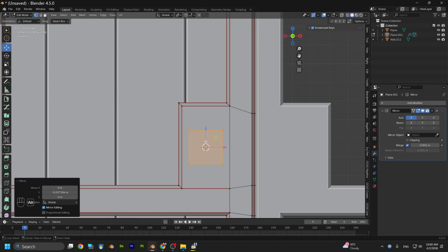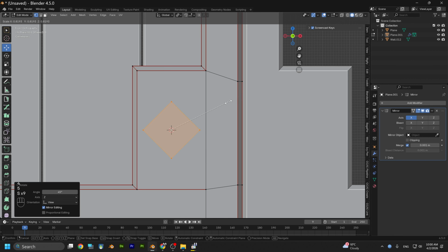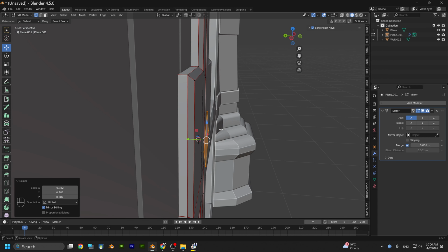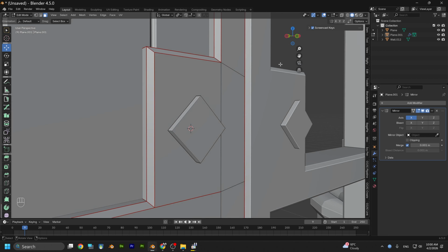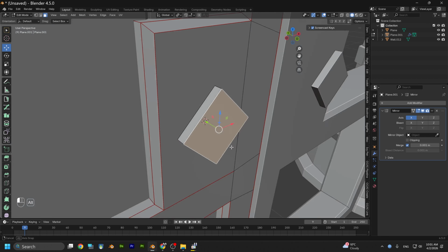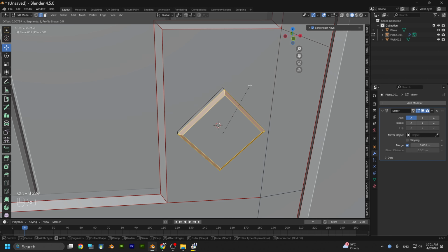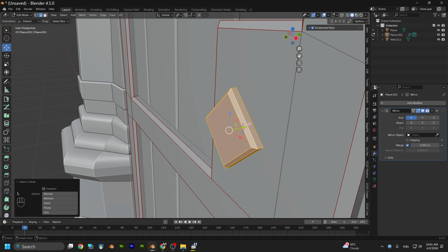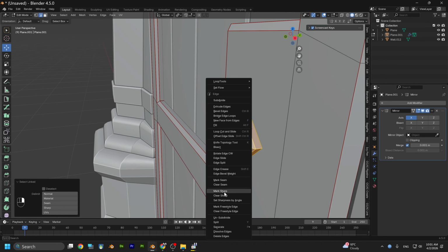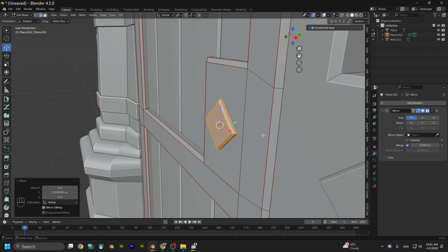What happened? Yeah. And let's rotate 45 and let's scale a little bit more down. So now we're going to extrude, and we can delete this face in the back. So let's bevel these edges like this. Select all, and actually, you know, we can mark a sharp and mark a seam, and let's move this back to be in position.